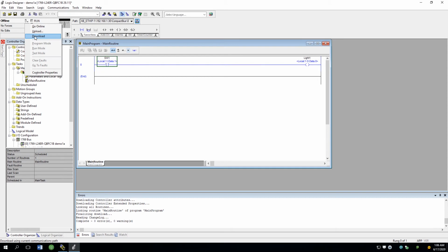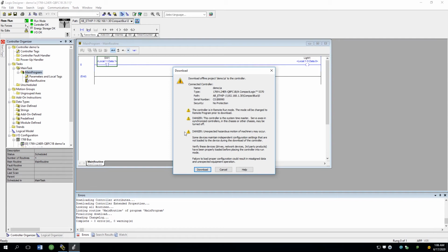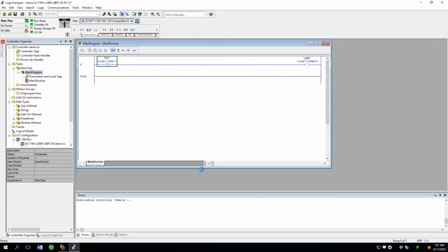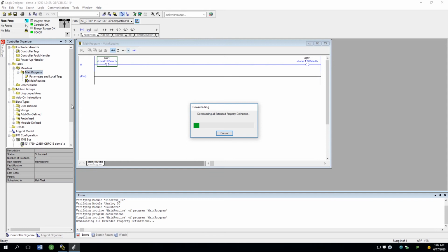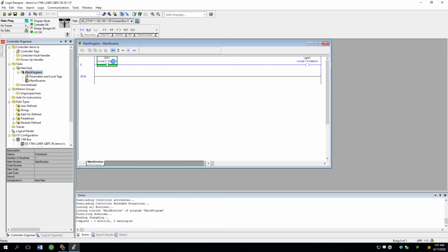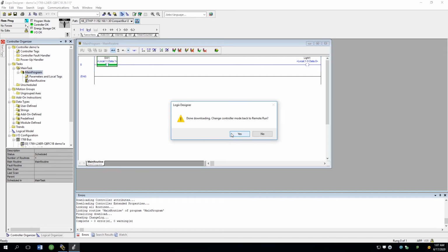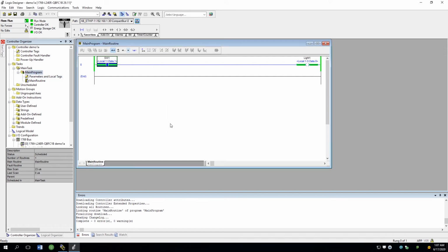Now we're not in the lab, but if we had a camera in the lab and we could see what was happening on this PLC, light 1 will probably come on because switch 1, or data 1, is a normally closed switch. So we'll see if this light does come on. I expect it will. Okay, and it did, just as expected, because this switch is closed and the light comes on.